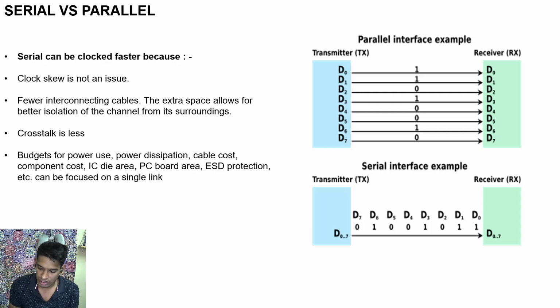By skew, what I mean is you're sending one clock, but you're receiving something different, and you're sending one clock to another circuit, and so both circuits will get different versions of the clock. Clock skew happens because the clock is being sent in a physical wire, and the wire will have some attenuation. It will have some delay.